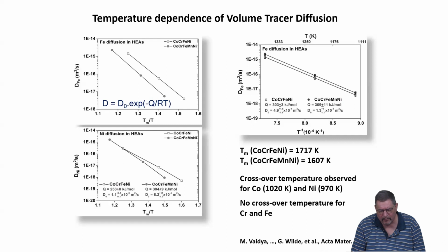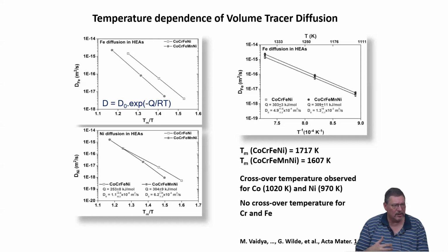And basically it also shows again small differences, but in tendency the diffusivities for the high entropy system are reduced as compared to the medium entropy system. So one could say, yes, this is an indication for sluggish diffusion because the self-diffusivities at given homologous temperature for the high entropy alloys are lower than for the medium entropy alloy. Word of caution again, the differences are small.